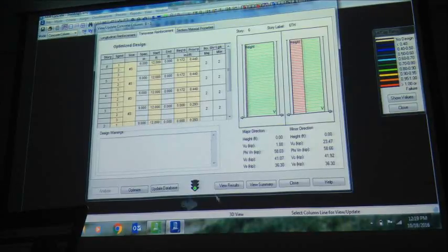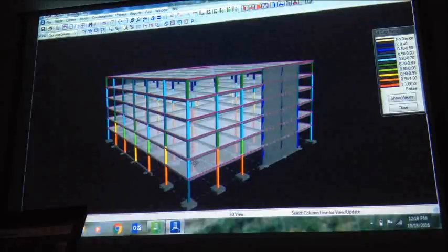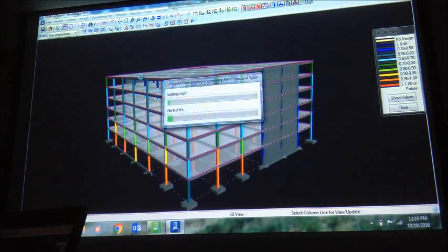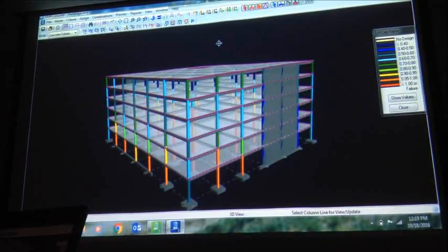So you have done the beam designs, you have done the column designs. Now, obviously there are some red flags. You need to have a larger one. Let me go quickly to the laterals. Once we are done with gravity, beams and columns, we will go to the lateral frame and then come back for the shear wall design, because shear wall designs are not only for gravity, they are actually also for lateral.